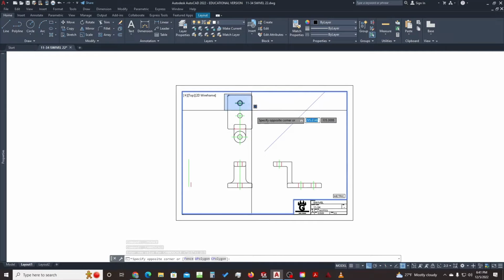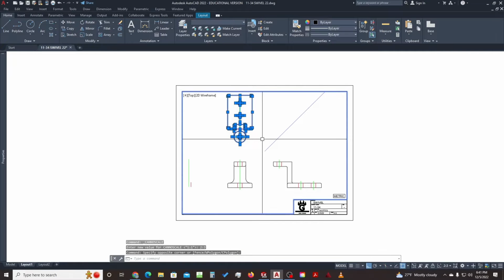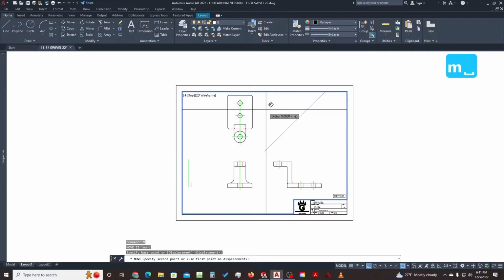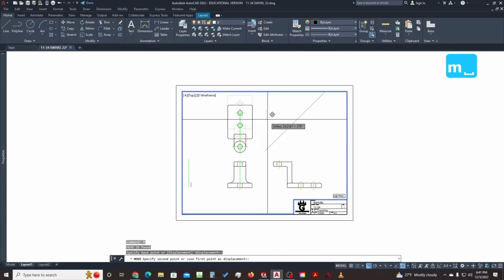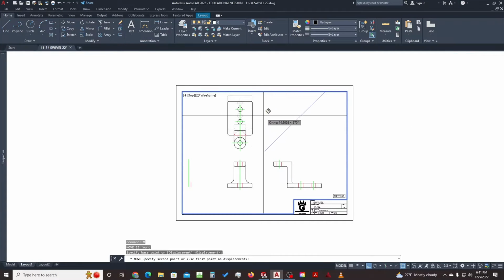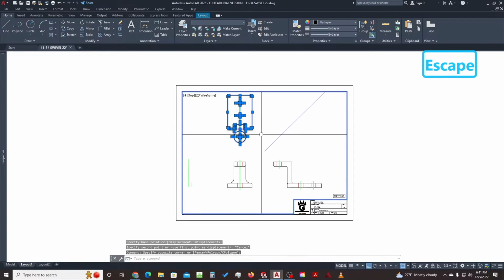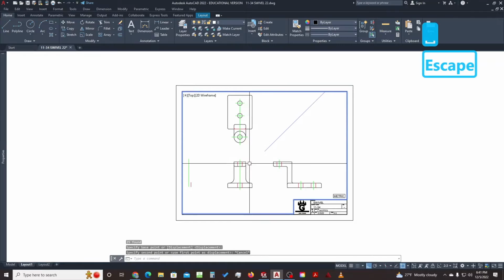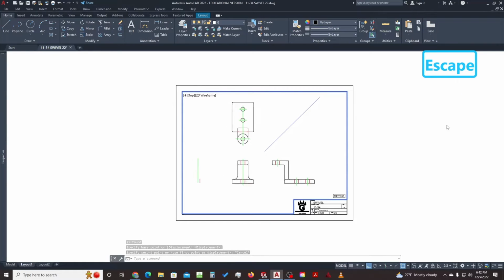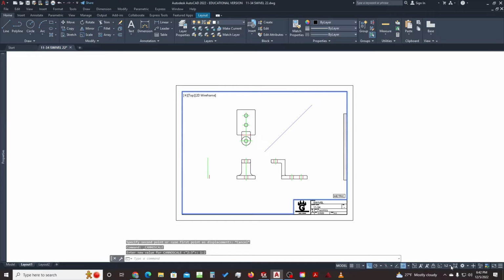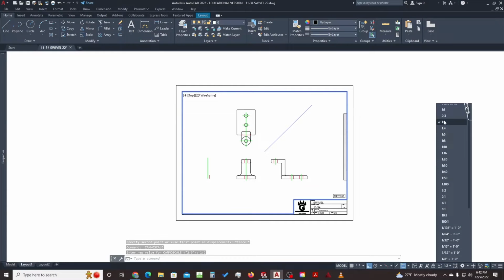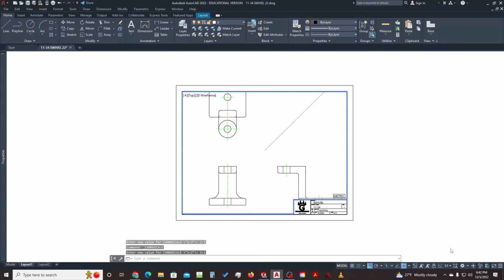If I wanted to move this down a little bit, this would screw up my alignment with my 45 line, my miter line, but it would allow me to fit everything maybe on page. I'm going to wait because I don't want the nose of this piece to be that close to this part, especially since we're going to add dimensions. Let's check another scale. 1 to 2 zooms us out. That might be the one we have to go with. And then 1 to 1's too close.